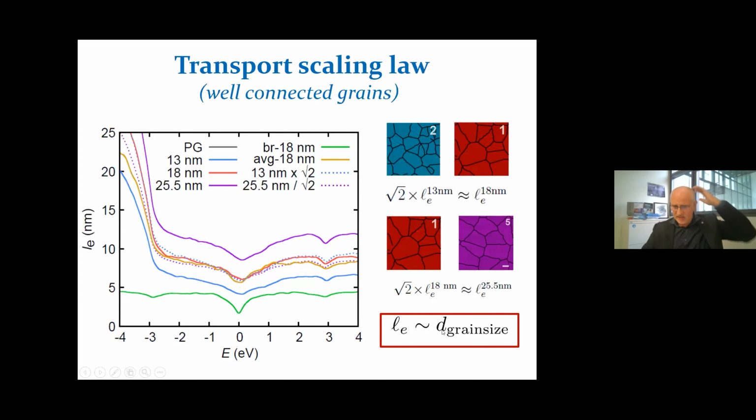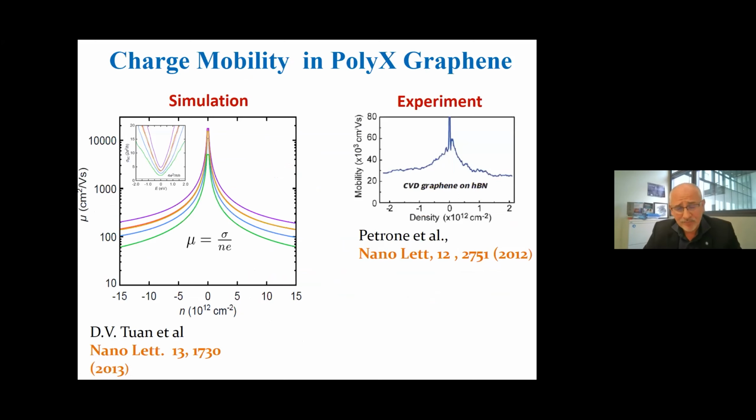It was really linear with the grain size. So it looks almost obvious, but here you come with the quantitative factor that controls the mean free path. And if we simulate the mobility also as a function of the grain size and the charge density, we could connect and compare with the experimental result.